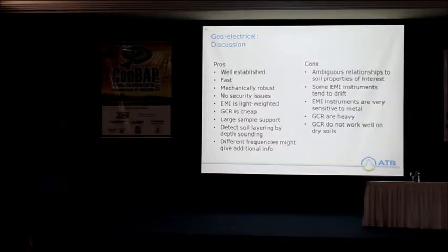Geoelectrical conductivity sensors are well established. They are fast, mechanically robust, and there are no security issues. The EMI is lightweight compared to this. GCR is cheap. They have a large sampling support to measure a big volume. They can detect soil layering if you have many depths of investigation, and different frequencies might give you additional information.